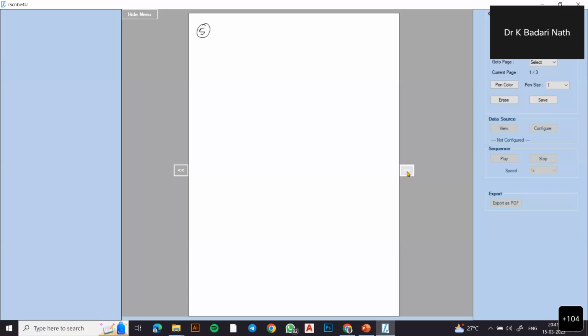The 4th one you use to add a set of numbers, if you want to repeatedly do certain things. Now the 5th one is called the indexed addressing mode. I'll give an instruction example and then we will analyze that instruction by a simple program. Add 4 of R0 into R1.